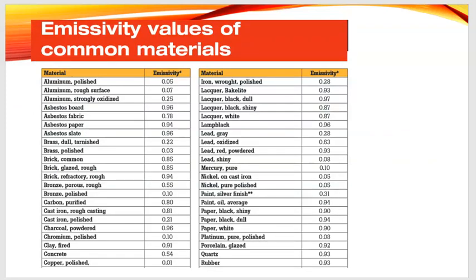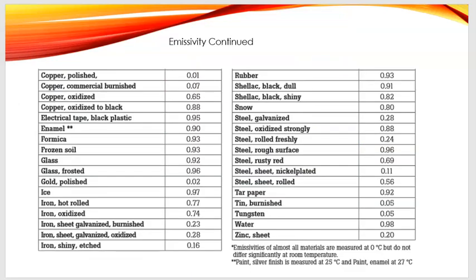And there's just some other emissivity values. If you'd like to pause and look at some of the concepts there, it's kind of interesting just to see what an infrared camera is going to do for you. Again, a few more of the different items that are out there. And you'll notice, maybe paint's not on here, but if you get paint, they have a fairly consistent emissivity, as I already mentioned earlier, that a black paint will have the same emissivity as a white paint. You'll see the same temperature, assuming there isn't any light energy or sun energy coming from a different level of the spectrum coming into it.